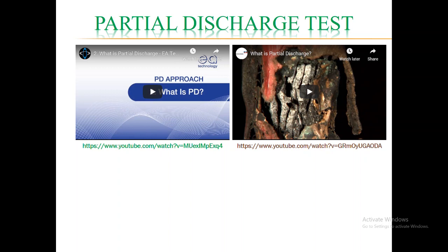In the case of the dissipation factor, broadly known as the tan delta value, it was observed that tan delta was voltage dependent, so it became a criterion for monitoring high voltage insulation.